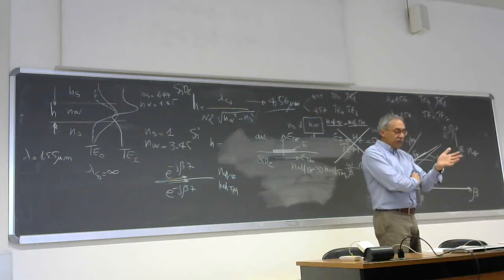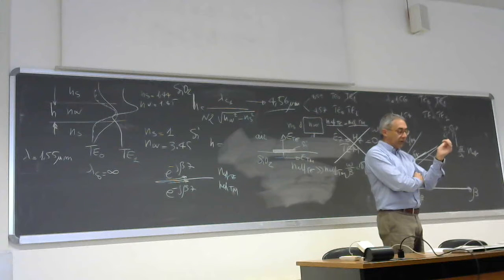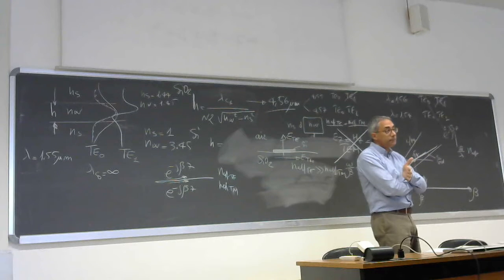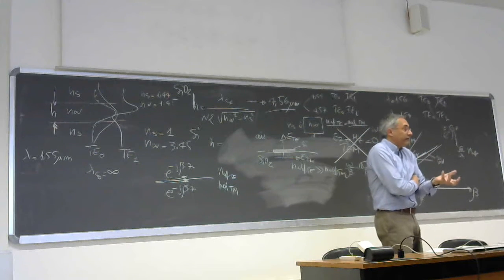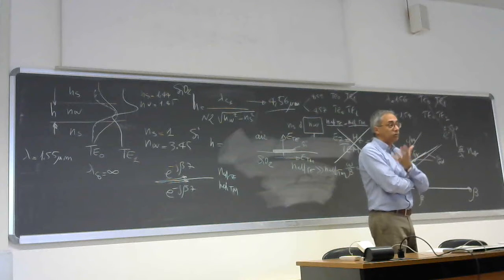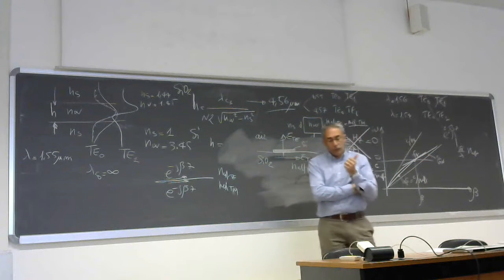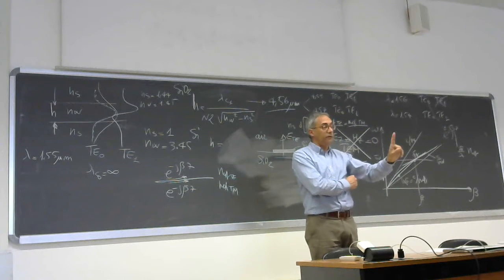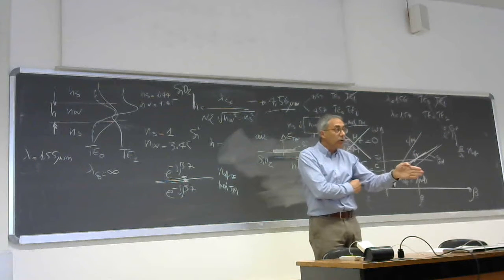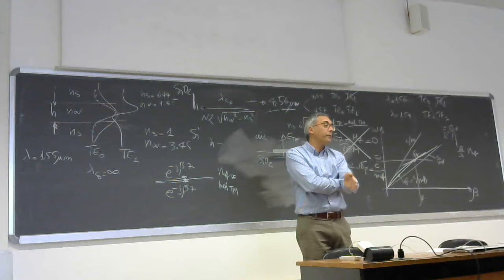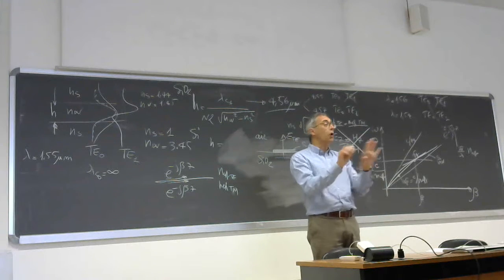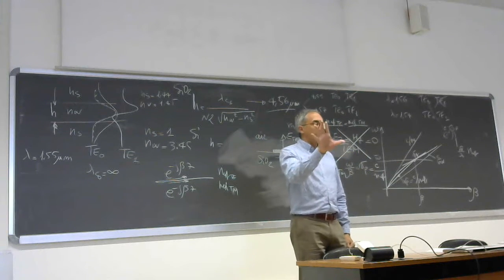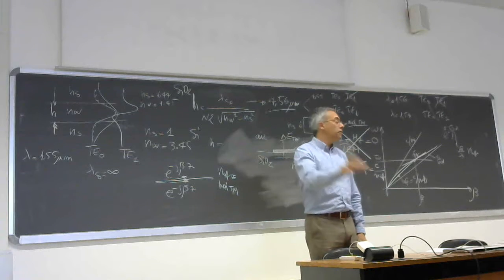If at some point of the link you use a photonic device, this must be polarization independent, because otherwise the behavior of the device depends on the polarization. It's something that you don't want. So either you control the polarization when it arrives and you put your field in the right position, or you use a polarization independent device. You have these two options. There are no other options. Okay? So assuming you wanted to use a polarization independent device, how to do it?